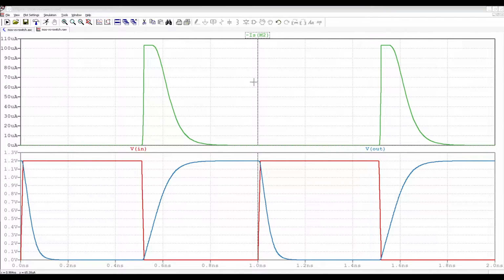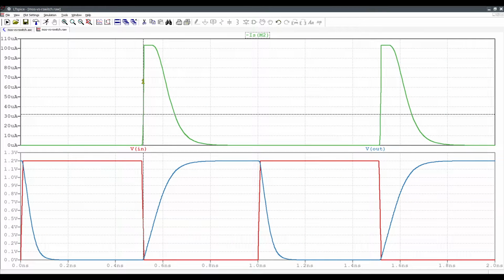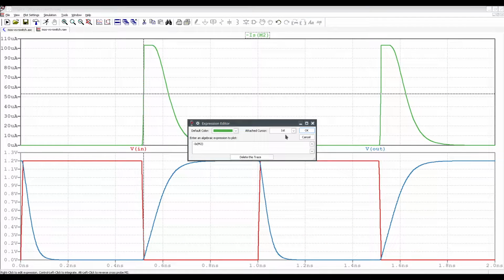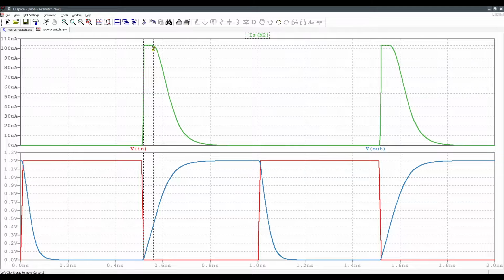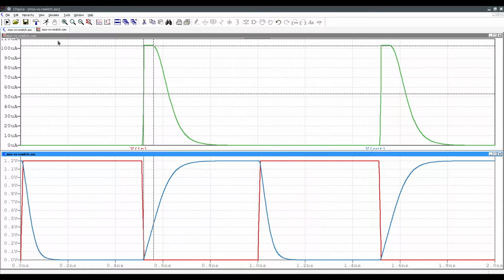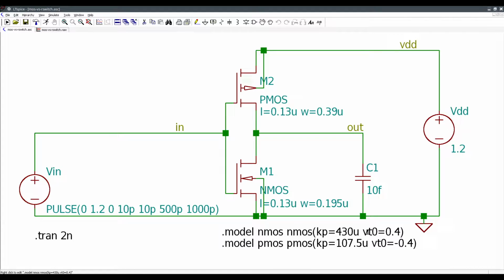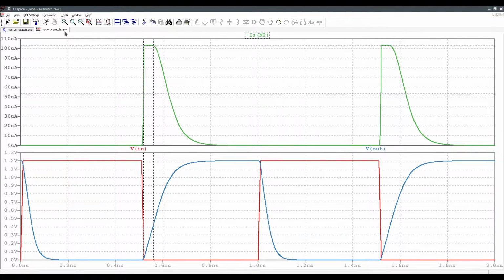What I really want to point out here is this region from cursor 1 to cursor 2. In this little region, the drain current is constant. And in fact, from this spot down here on the voltage rising up, that is when the transistor truly is in saturation mode. I'm using a very simple transistor model with these parameters, and in the simulator, this pulls really the textbook equations for MOSFET, the one that we use for hand calculations.